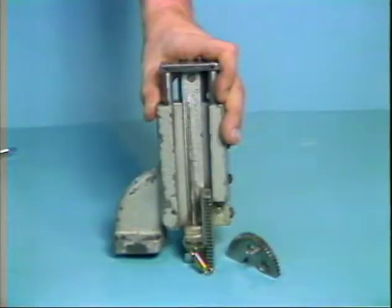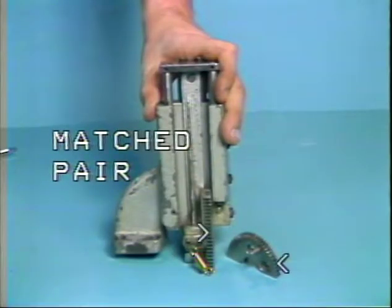The circle gear and rack gear are a matched pair. When the attachment is stored, the circle gear should be attached to the attachment. If one of the gears becomes worn or damaged, both gears should be replaced as a set. Mixing of the gears from different units may cause improper operation of the attachment when installed on the machine.